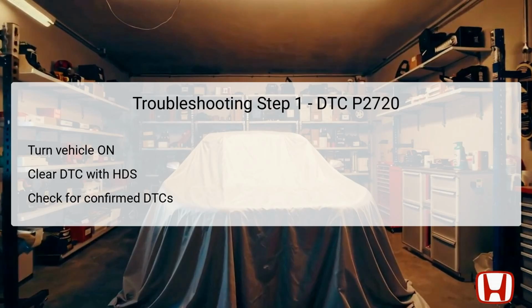After clearing the codes, start the engine and wait for at least 1 second. Finally, check again for any pending or confirmed DTCs using the HDS. If DTC P2720 appears again, this confirms a repeated issue and the troubleshooting can proceed to the next step. If not, consider the possibility of an intermittent issue and inspect the connectors and terminals for any signs of wear